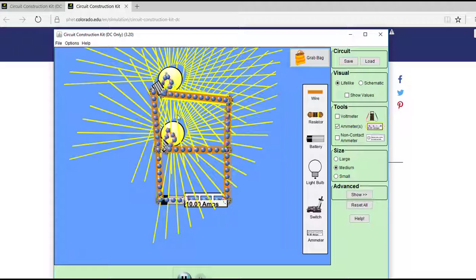One thing I should mention though is if you've got 50 volts battery voltage and 10 amps, that means the effective combined resistance of these 2 10 ohm light bulbs is only 5 ohms. Remember, the resistance times 10 equals 50.